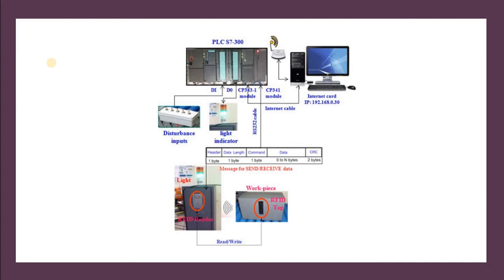In the CPS model, the communication that we've seen just now is laid out in this diagram. We can see that the physical devices that serve as sensor, which is the RFID reader and switches, are connected directly to PLC that serve as a controller on the physical part of this model. And the cyber part is handled by PC, in which 3 independent agents for each PC that serve different purposes were interconnected to manufacturing execution system to decide on appropriate action for the PLC to execute.